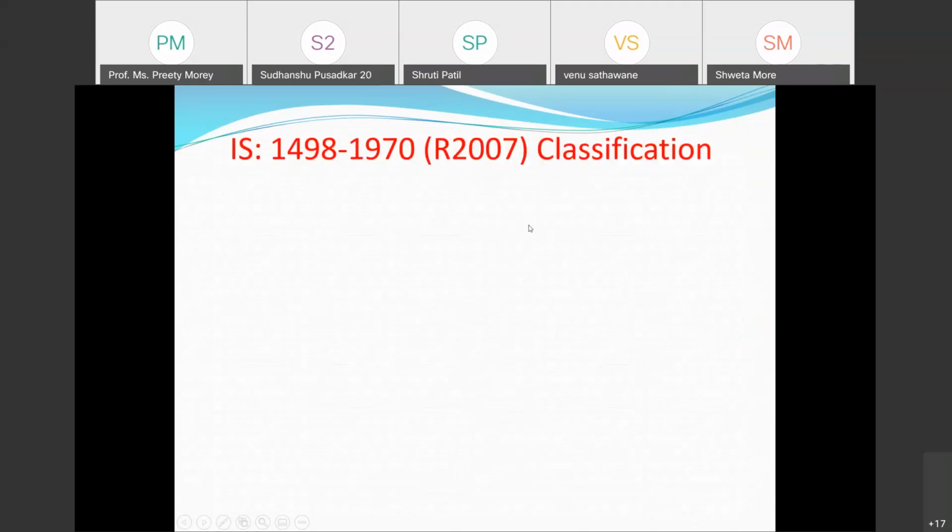It is on the same recommendation, only the difference is the plasticity chart which we had used in the Indian standard method. It is only a line curve, whose equation is PI equal to 0.73 (LL minus 20). The US classification has made two classifications, low and high, that is L and H plasticity, whereas the Indian standard has made three classifications: H for highly plastic compressible soil, I for intermediate compressible soil, and L for low compressible soil.